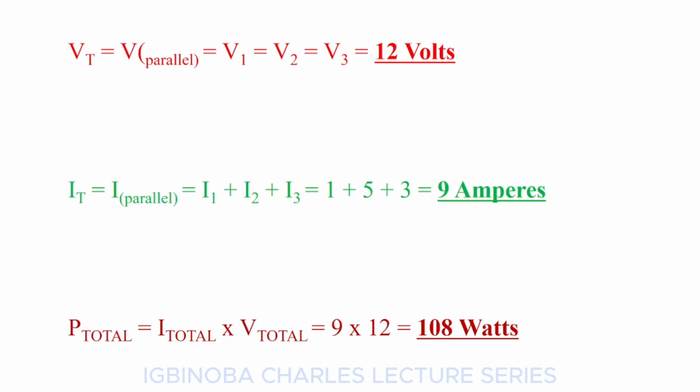It is very important to note here that when panels are manufactured, manufacturers usually put the power of the panel on the nameplate. Some are rated 100 watts, 150 watts, and so on. These power ratings are usually abbreviated at the back of the panel as WP, which means watts peak.